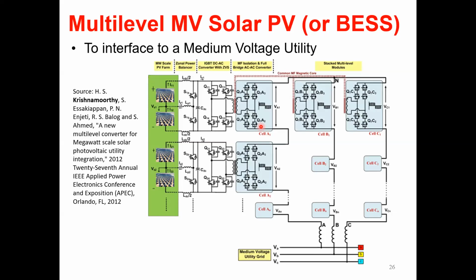So because of that, we series stacked the different converters like this, and then eventually got a 13.2 kV AC. Of course, we implemented it in a scaled-down lab prototype. But for this concept, there are some aspects of the voltage balancing, which we published in another paper. But considering this as a talk on solid state transformers, I don't want to go to the control side.